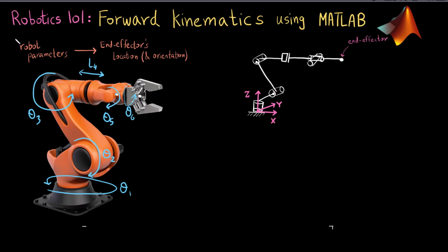So let me start out doing the forward kinematics. First and foremost, I am going to be writing the first homogeneous transform, which I'll call H1. It is simply going to be a rotation about the z-axis, which is this one, theta 1.